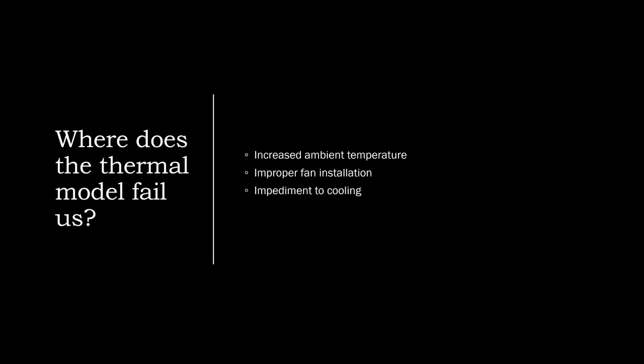Seen this recently at a few places. Sawmills are particularly vulnerable to this. Motors have cooling fins, and that is part of their heat dissipation design. And if things like sawdust or kaolin, other materials of a powdery-like substance that can form together, block the heat dissipating from those fins, that is also going to affect the motor heating and make the thermal model that much more inaccurate.